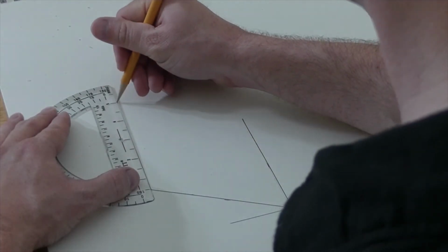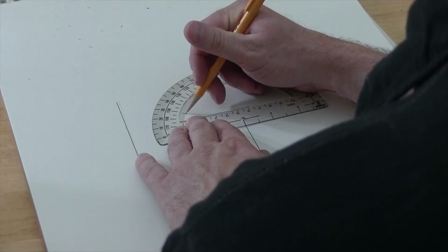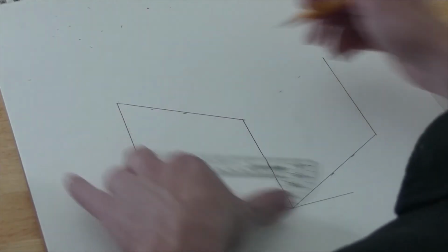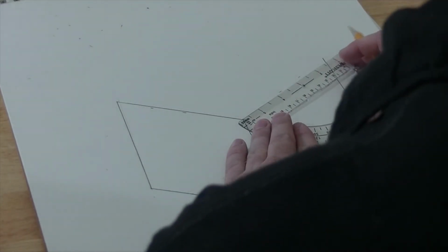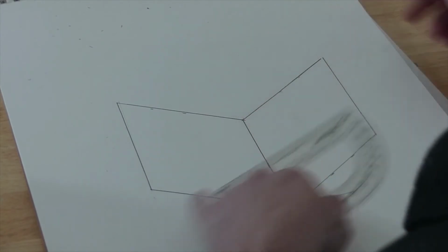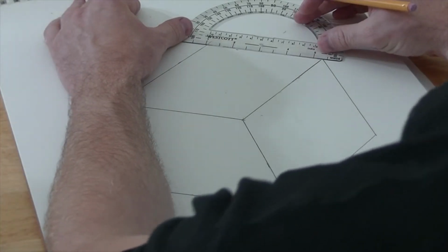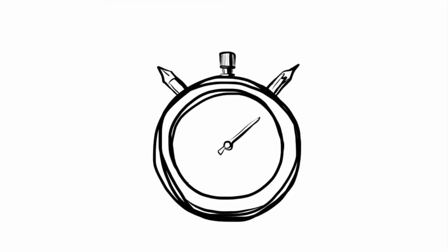Then, erect vertical lines at each corner the same length as the one in the center. Finally, complete the top of the cube with 4 more diagonal lines, making sure to keep all parallel lines in the same set parallel with one another. Like orthographic and oblique drawings, isometric drawing is a paraline system. Okay, start.